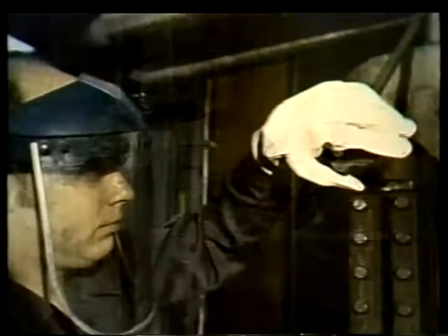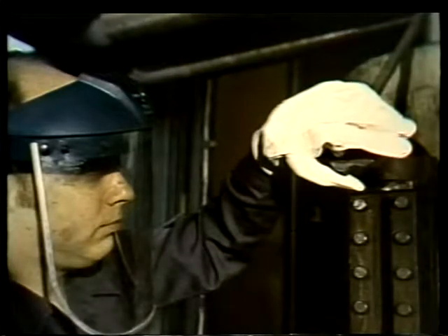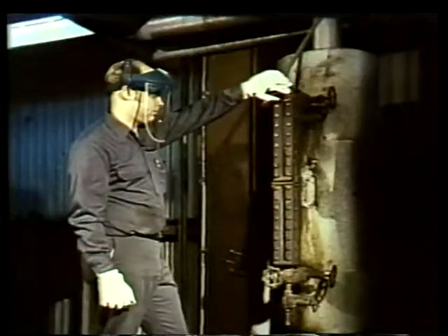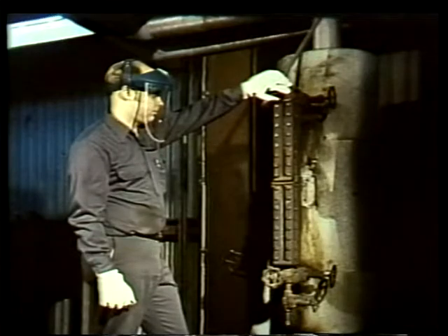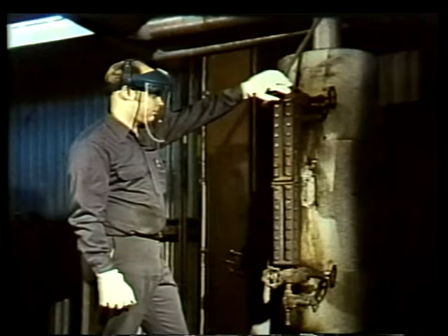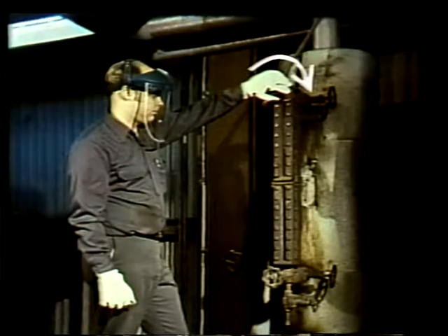Gloves and full face protection must be worn while you do this. Open the drain valve just far enough to permit a small amount of flow through the gauge. Let the gauge warm for about 15 minutes. After the gauge warms up, close the drain. Check for leaks. If any are found, isolate and depressurize the gauge by closing the upper gauge valve and opening the drain.